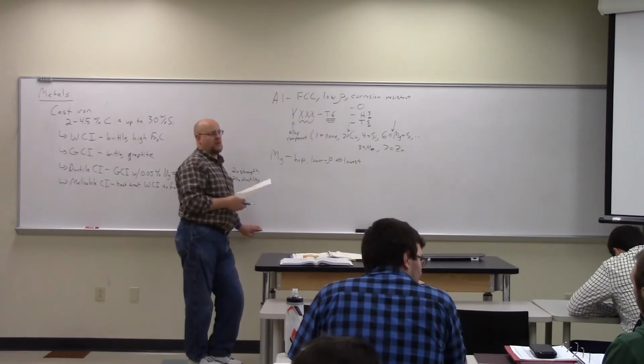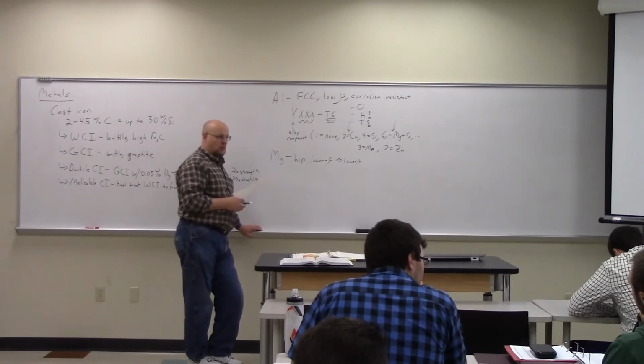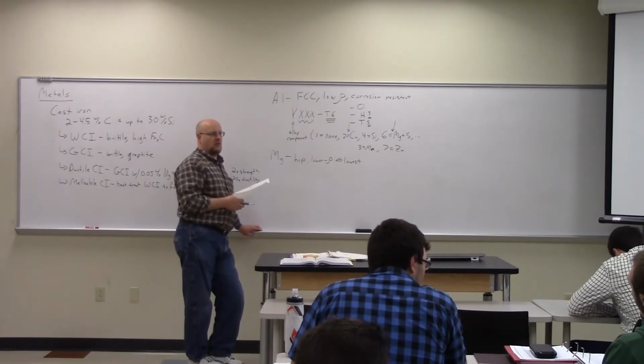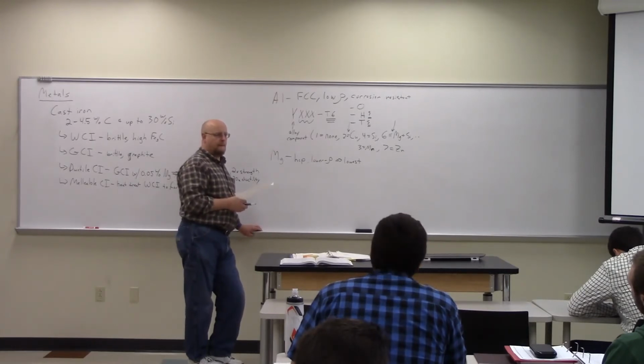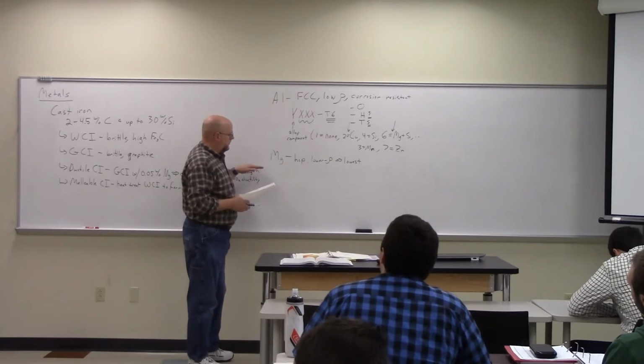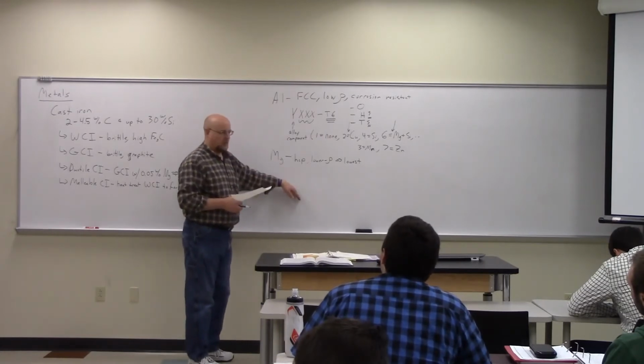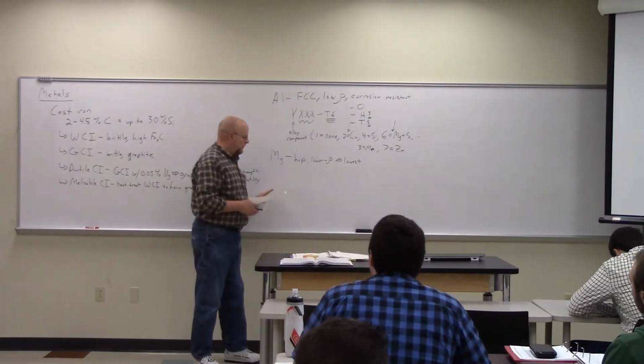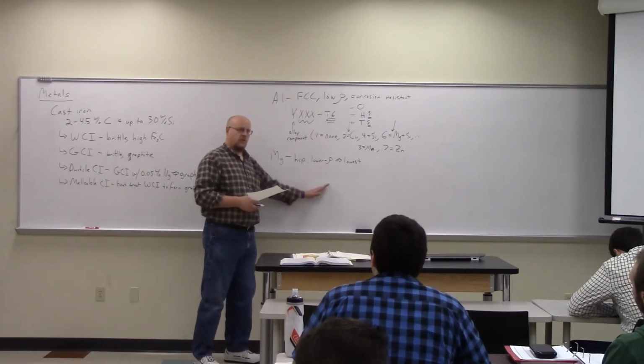In fact, typically as you alloy things, if you just put a little bit of something else in there, it typically lowers the melting point, unless you're doing it as a solid solution. You notice all of our curves, right after the melting point of the pure material, the curve went down. The exception is the full solid solution, where it actually went up for one side.